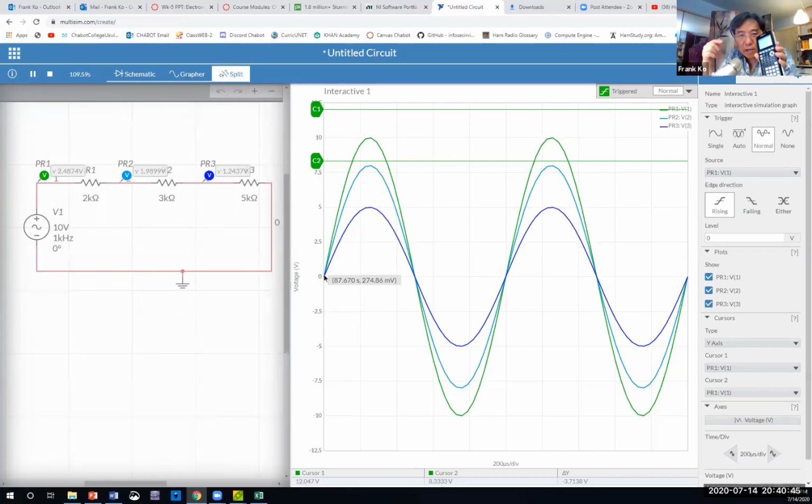While that number is on your calculator, that is the time for one cycle. There's a quick two-button push to convert time into frequency. You hit your reciprocal key, 1 kilo, and then you hit equals.